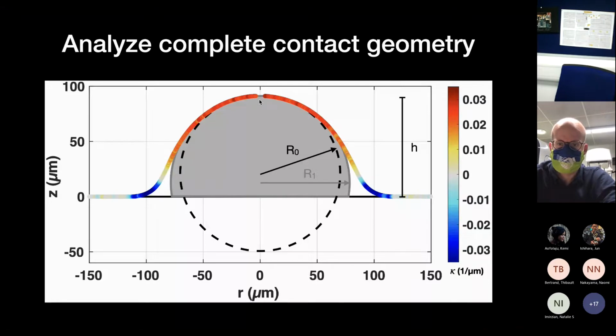One of the ways, actually, is the curvature, which I show you here, another strong indicator of what's happening in that fluid contact regime, where this is a positive curvature. If you like to think in terms of Laplace pressure and wetting and curvature, a positive curvature for a pure liquid would mean a positive back pressure.